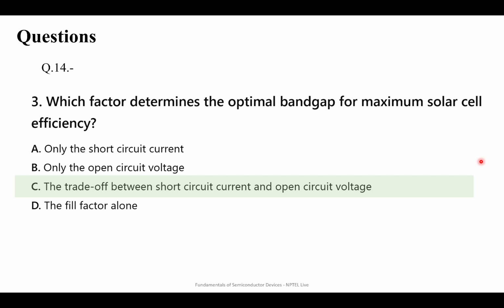Yes, sir. But you said 1.3 is the maximum band gap for single junction. Not maximum band gap, optimal band gap. The best band gap you should have to get maximum efficiency. One material can have a band gap of 0.8 eV, then silicon 1.1 eV, then for gallium nitride you have 3.4 eV, right? But what is the band gap that will give you maximum efficiency?